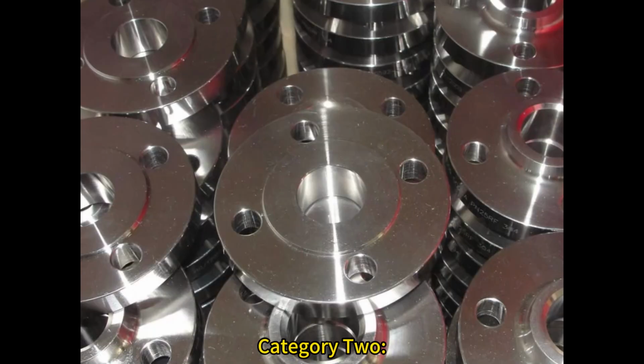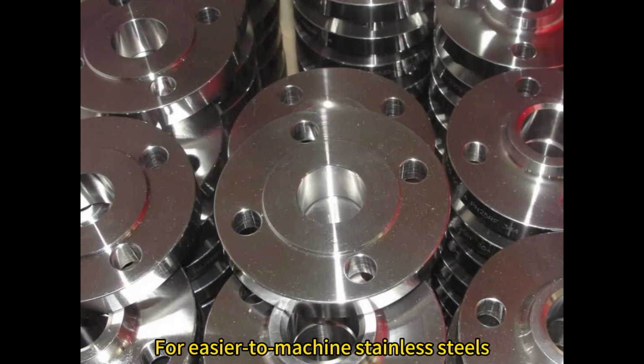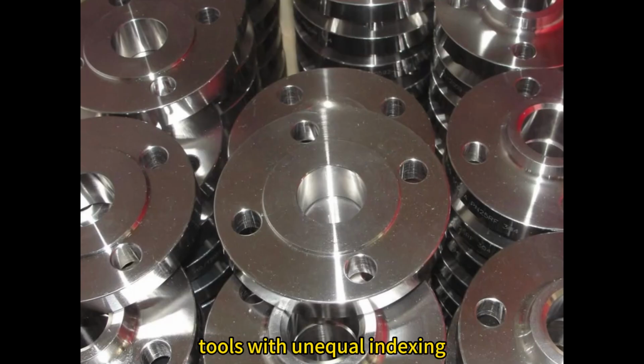Category 2. Stainless steel materials. Let's break this down further. For easier-to-machine stainless steels, such as 303 and 304, we recommend using dedicated stainless steel tools. For example, tools with unequal indexing and unequal pitch designs work well. If you're a small shop doing small batch processing and don't want to buy dedicated stainless steel tools, you can substitute with tools from Category 1, which are designed for steel materials.